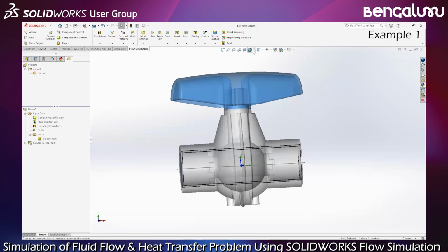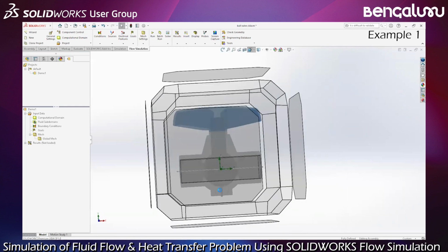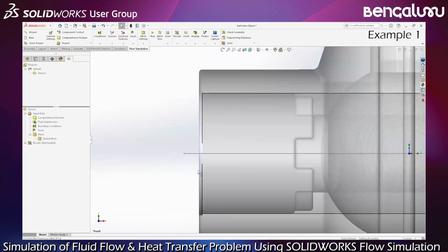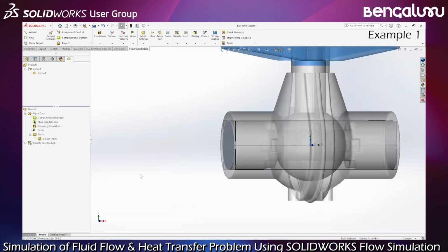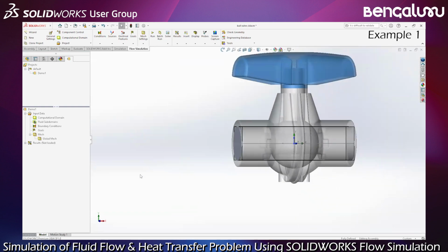If I project, for example, here, you can see the limitation of the fluid domain is on the internal face of the lead I created, okay? By the way, there is an automatic leads creation. You can do it manually as well. Just create an extrusion to fill the space here, and that's it.